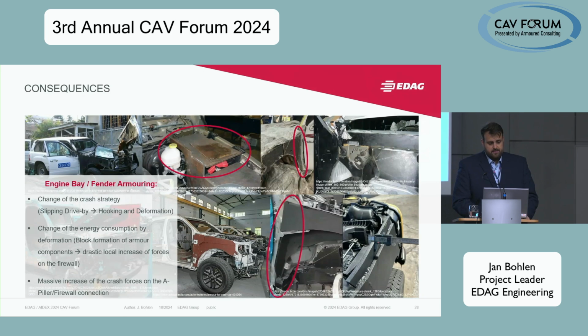And what we see here quite often in the conversion is engine bay or fender armoring. It's a good thing to protect the engine from ballistics, but spoken from a crash perspective, this is quite problematic, since in the end you change again the crash strategy of the OEM.